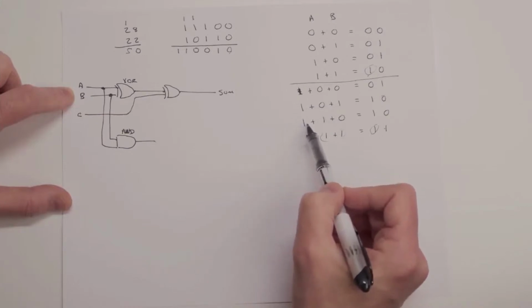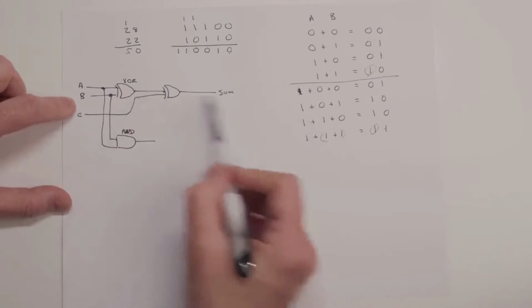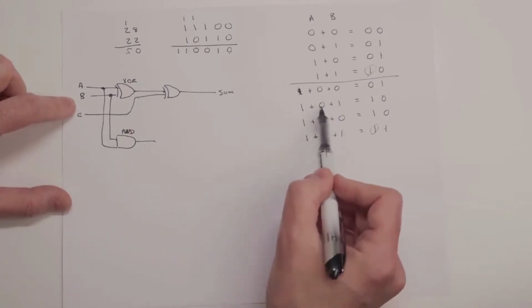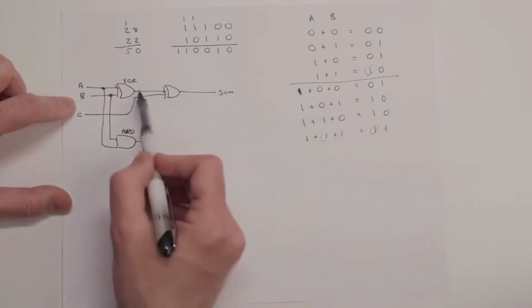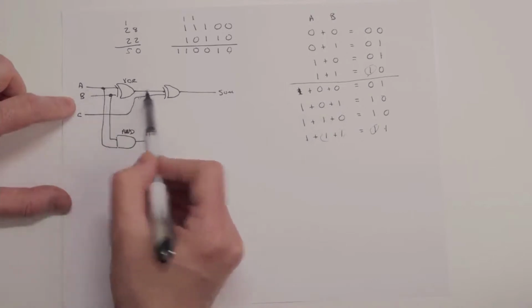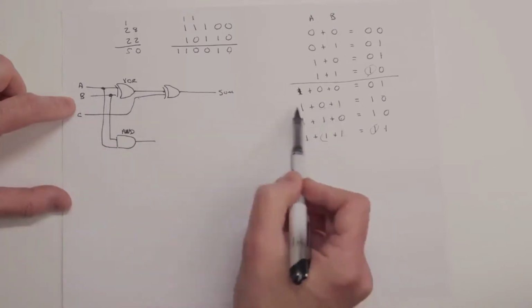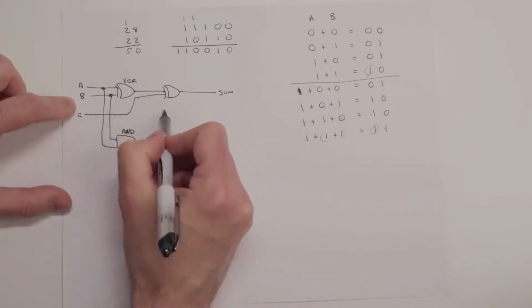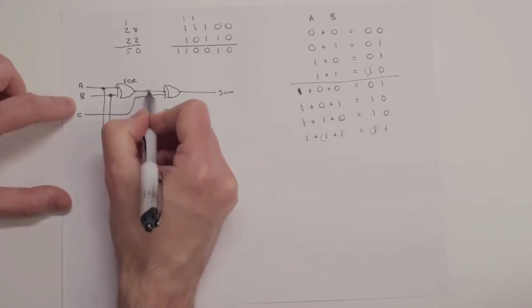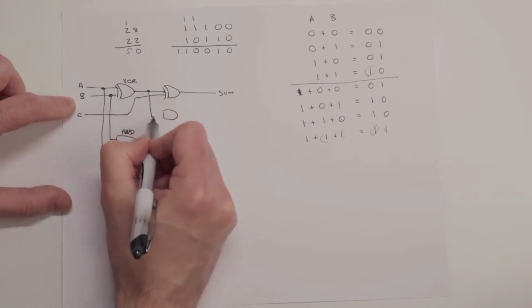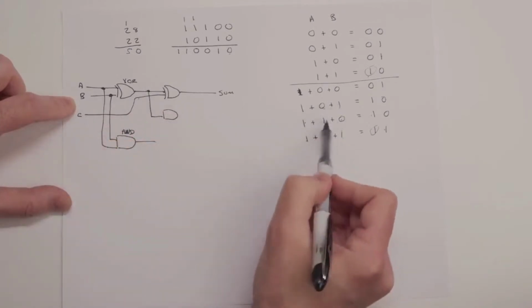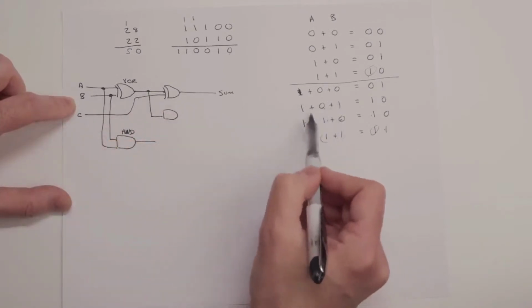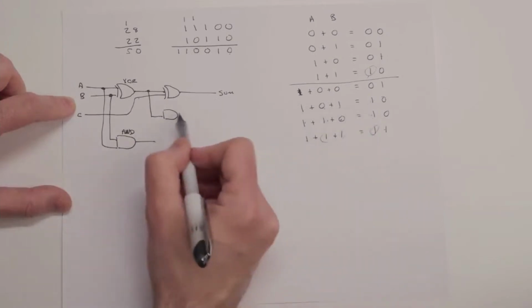And so what we can do is we can actually say, well, if we have the carry and the exclusive OR of A and B, we already have that exclusive OR of A and B. So if A or B is a 1 and we have the carry, then we want this 1. So we can actually just AND the A XOR B, which we already have, with the carry bit. If the carry bit is set, then we get this 1 here.